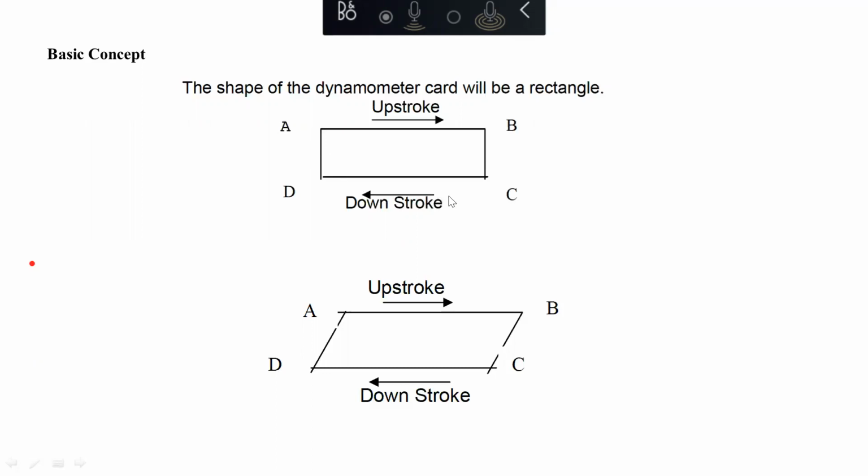But when your tubing is not anchored, you are going to see a rhombus-shaped type of dynacard, because you are going to see a gap here, which is because of your tubing stretch. During downstroke, your tubing is going to expand, because all the fluid load as well as the sucker rod will act against the tubing. And during upstroke, this is your contraction.